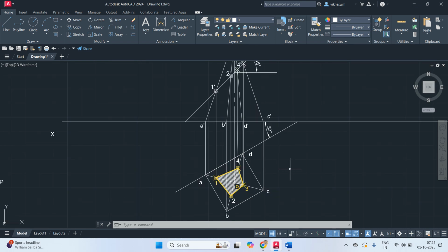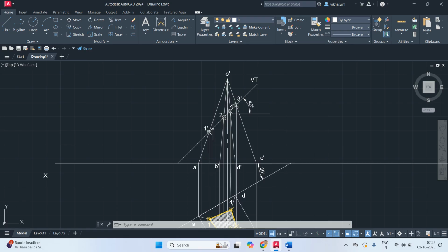So once you cut the solid and remove the top portion, and after removing the top portion, when you see it from the top, you can get such a sectional view. So here also you have to highlight it. So again take a line. After cutting, we remove this top portion, only the bottom portion remains. So you have to highlight that bottom portion. So again start from 1. Only highlight the bottom portion, the edges that are below the cutting plane.